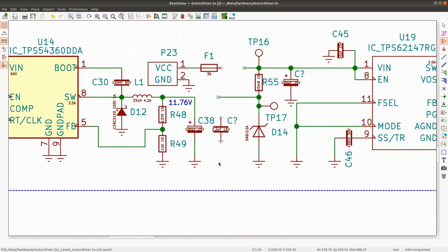The reason for doing this is that this would be a ceramic capacitor. It will lower the ESR a lot, and also it's not possible to determine the exact ESR, which we do need for our calculations for the compensation. We don't know the exact ESR until we have the components. So it's kind of a chicken and egg problem.